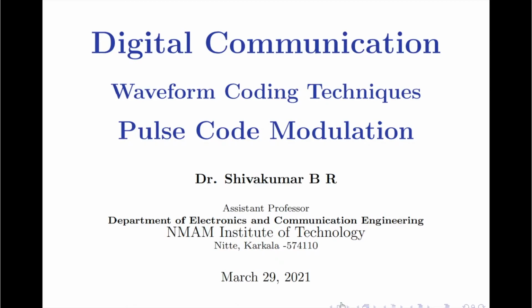In this video, I am going to briefly discuss pulse code modulation. Modulation is defined as the process of modifying the properties of the carrier signal such as amplitude, phase or frequency based on the information bearing signal. So, pulse code modulation is a method that is used to convert an analog signal into a digital signal so that a modified analog signal can be transmitted through the digital communication network.